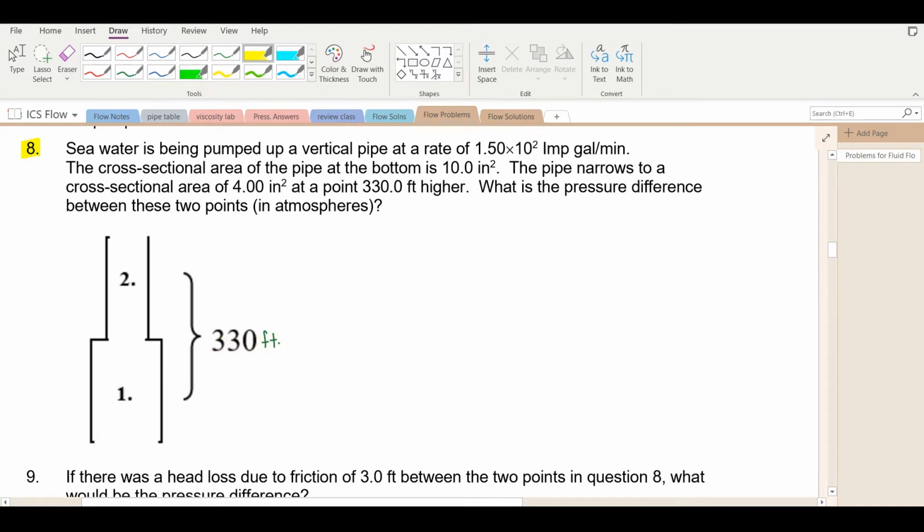That's a pressure difference. Now, if the water is moving, and let's say the pipe is of constant cross-sectional area, it's not constricting, but if the water is moving up the pipe, then there would be an additional pressure loss due to friction. Now, we're not given a value in the problem that we could use, so we'd have to leave it out. But the fact that the cross-sectional area of the pipe is decreasing means that the velocity is increasing.